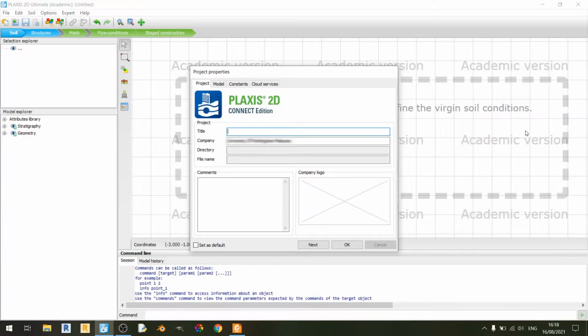In this tutorial, I'll be showing you how to do a NATM model in Plaxis 2D. So in short, for those that do not know, NATM stands for the New Austrian Tunneling Method. It's mainly used for mountainous areas where any tunneling is required. Excavation is usually done by inserting explosives into drill holes, and once the debris is removed, shotcrete or rock anchors are installed, and occasionally you might have other stabilizing methods employed.